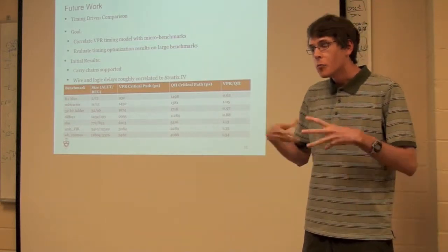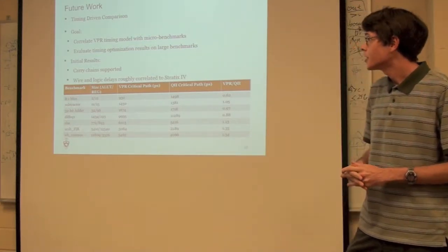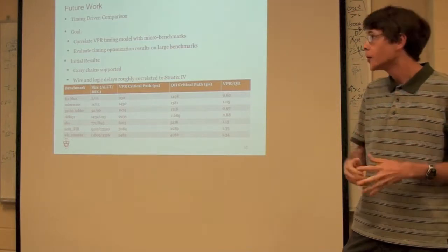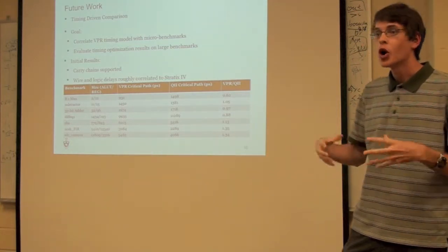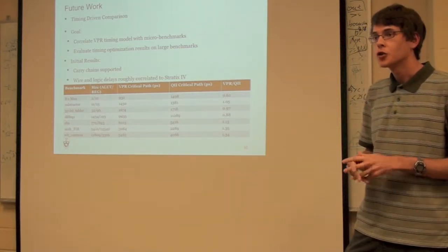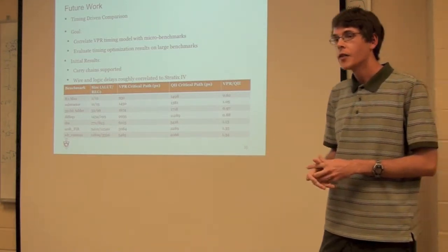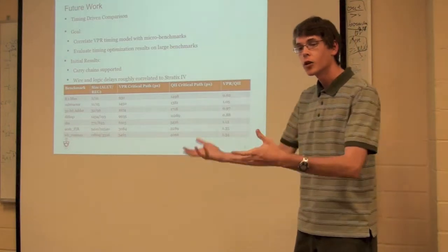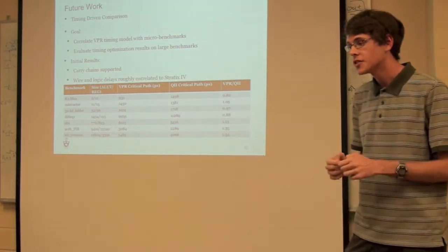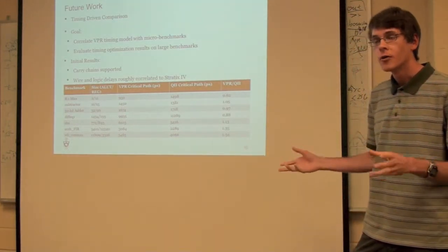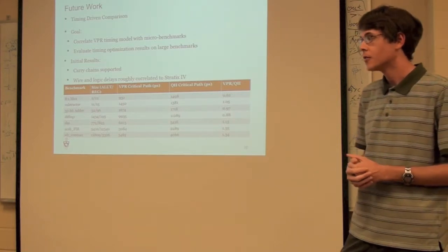The methodology we're going to follow here is to try to correlate our VPR timing model with a set of small micro benchmarks that shouldn't be affected too much by the different optimizations in the two tools. And then once we've done that, run our larger benchmarks and evaluate the results and see what quality of timing optimization both tools can achieve.